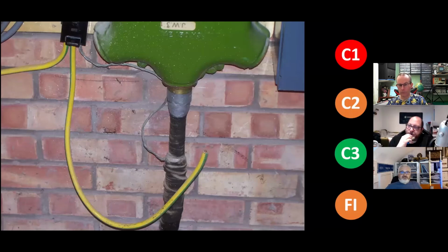My first thought is FI, shoot me. But the main earthing terminal, the connection point, is that Henley block on the top left. So if somebody's left that for the DNO, assuming that they would sweat it on or put on a clamp, the DNO haven't done that. You can see the DNO have sweated a braided, flexible steel tape and then connected that into that main earth terminal.